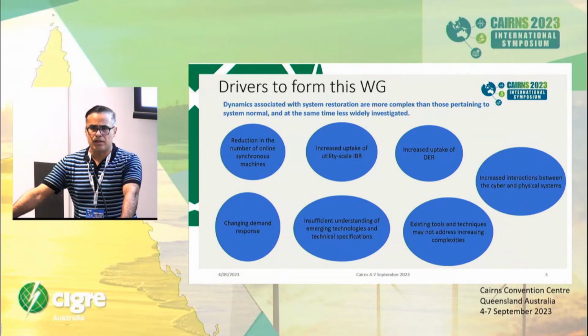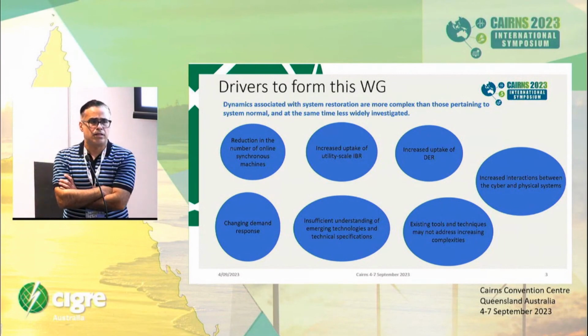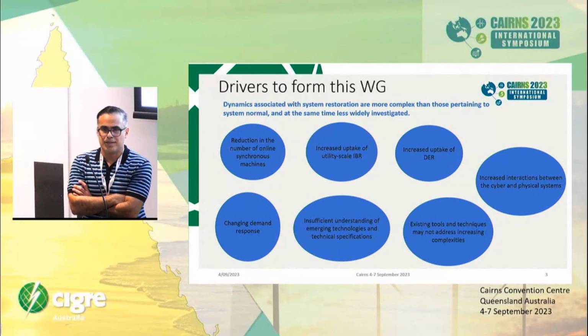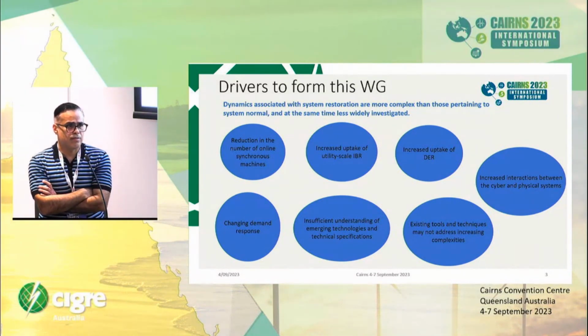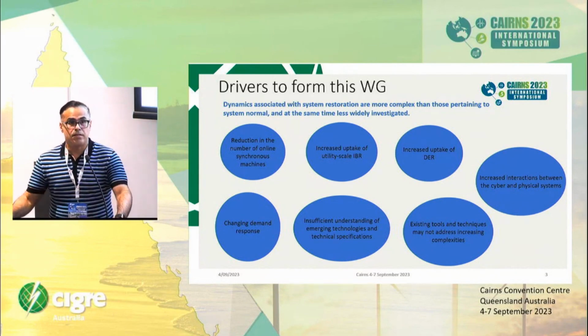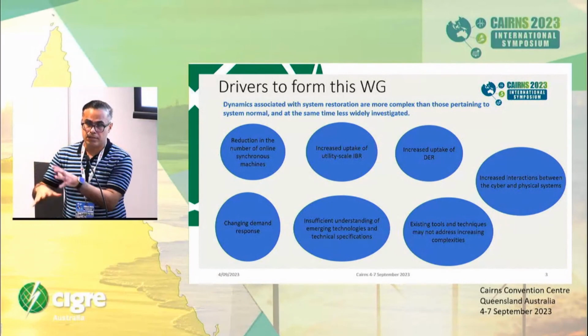Besides that, we're talking about larger scale generation, whether synchronous generators or inverter-based resources. But we should also be conscious that there is another element: distributed energy resources. There are more in some countries than others, but it's getting to the point, for example, in this country, where approximately 20% of installed generation capacity comes from distributed photovoltaic. Each one of them in isolation is obviously very minute, in the small kilowatt range, but when they all come together, it's in the range of several gigawatts, and they cannot be neglected either. And we're talking about the distribution side and low voltage side.